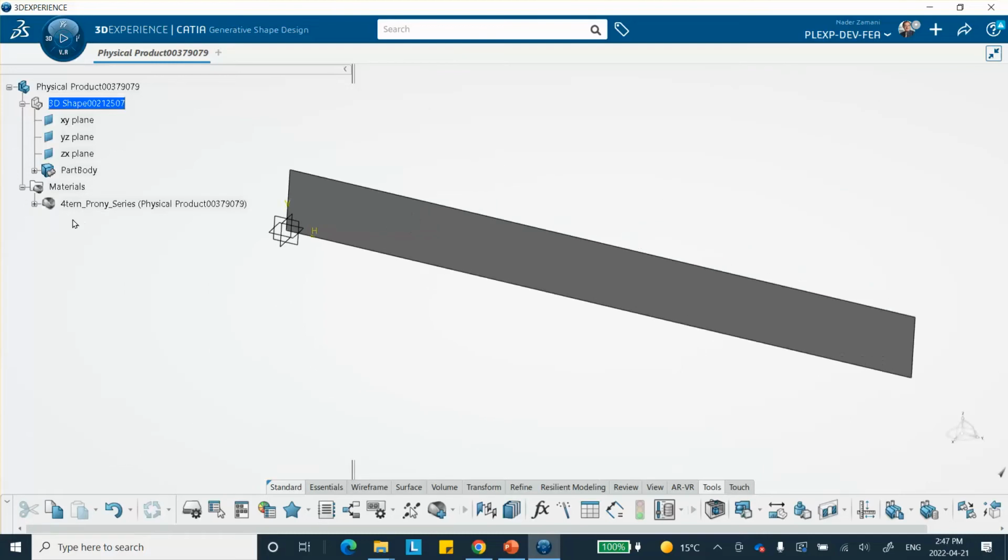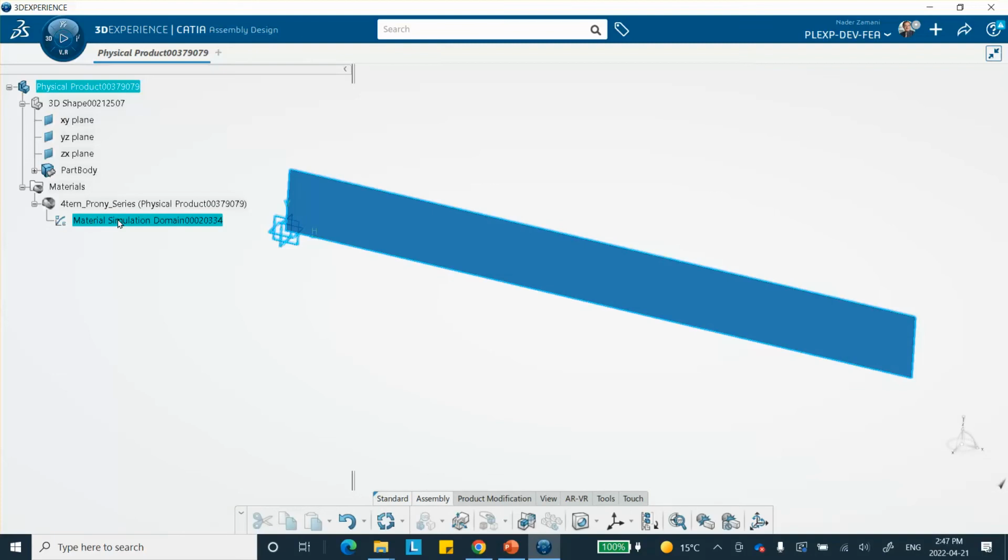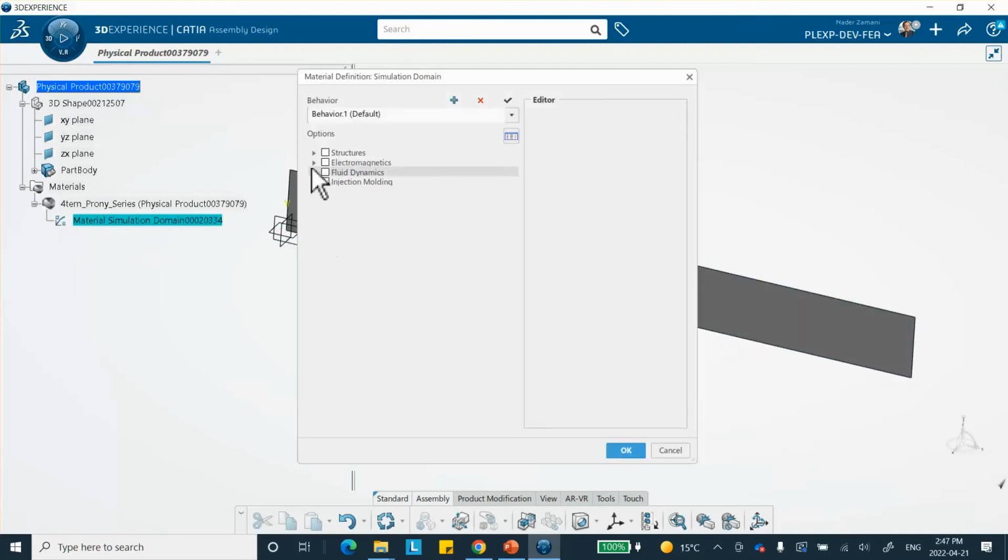And now we expand the tree and we can input our values here. So we go to material, this branch, material, structural. Now density is going to be put in this box, but we're not specifying the density.